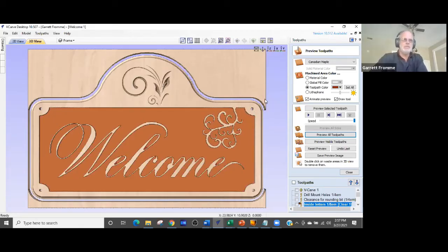That can be done just before the profile cutout, as opposed to putting a 1/4 inch down bit to start the holes, then switching over to some other 1/4 inch bit and then coming back to it. But unfortunately, because there's a lot of 1/4 inch work within this area, and this area has to get done before the cutout profile happens, that means that bit would be put into the router at least twice.